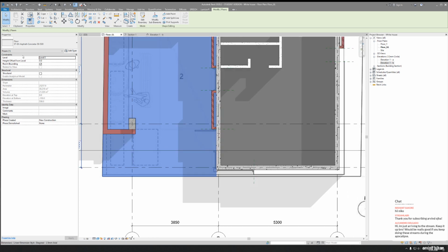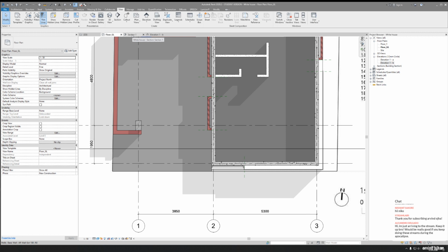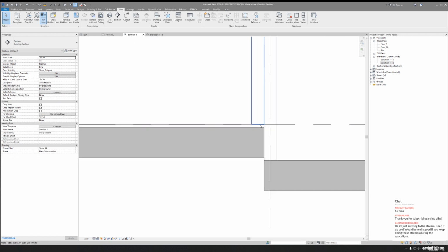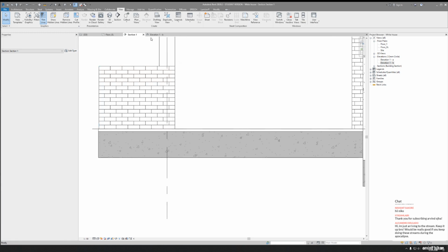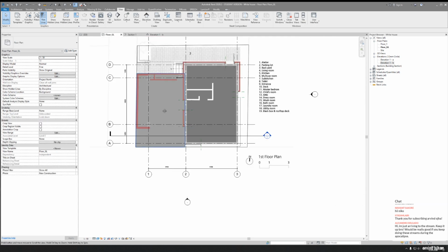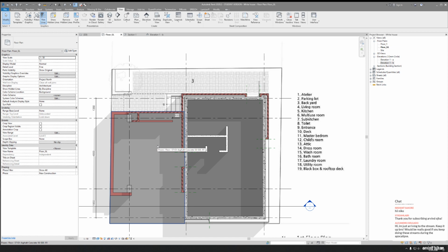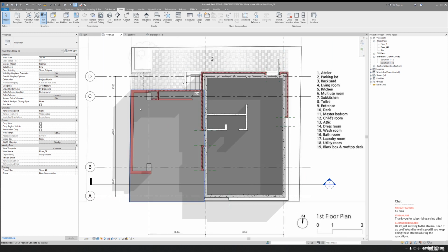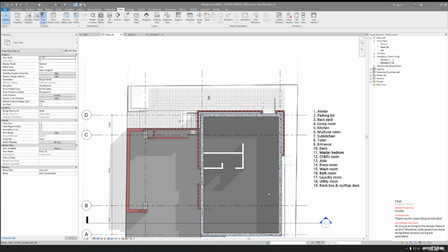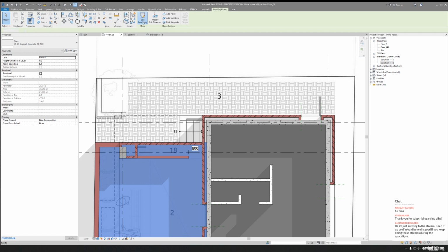Let's select it, and as you can see we get some thickness of the material here. Let's go back to the section view, and we can see now that we get this thick asphalt here. Okay, awesome. Let's go back to the floor, and now I will create one more. I think I will continue this. No, here's another floor, as you can see. Here I will use another floor, and here too, and even here I should divide it. We will do it later on, so let's make it one union. After that I will divide it.